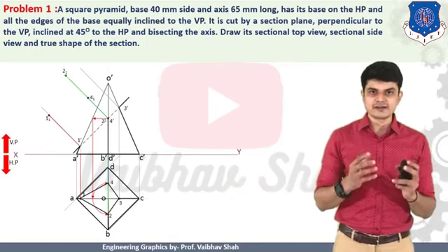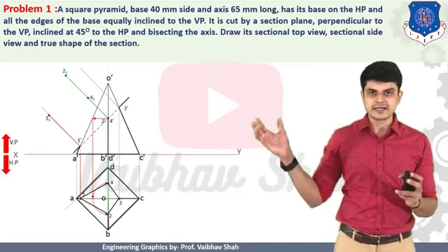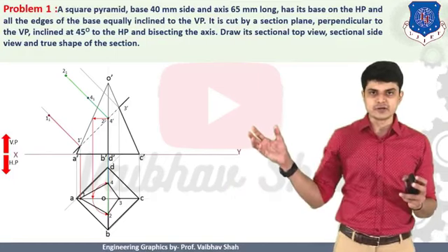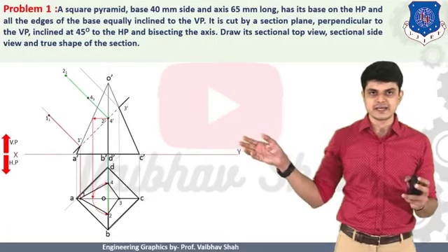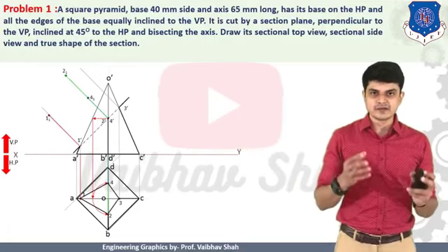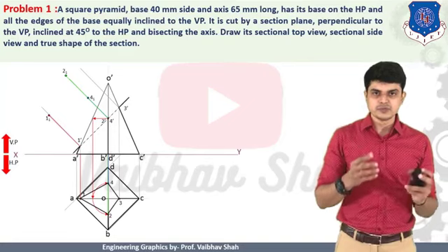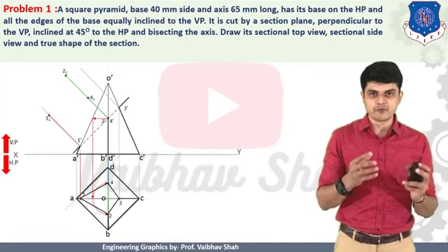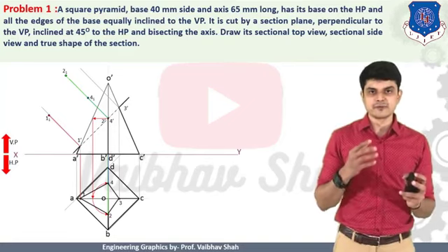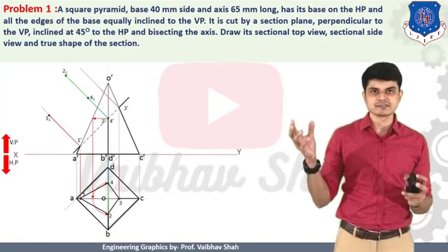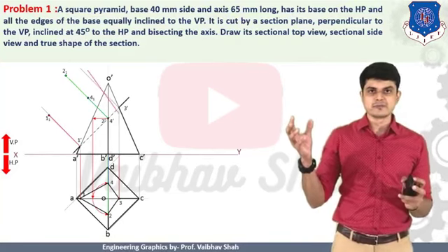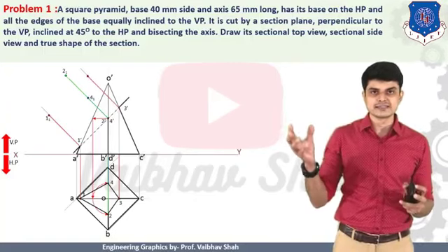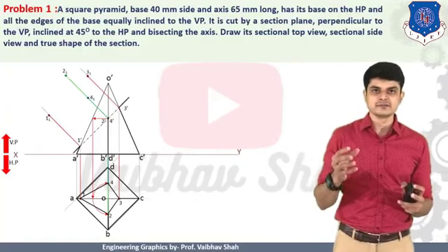Thereafter we should go to your cutting plane line. Find out the intersection point of 3 dash and your section plane line somewhere there. And after getting that point, you should put that rounder on that point. And you should mark your point 31 on that line somewhere like this. So you will be having your point 31 somewhere like this.